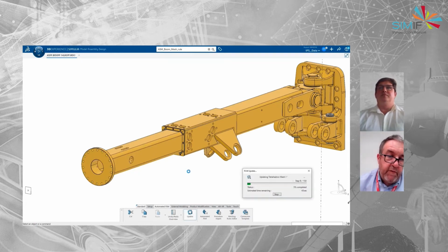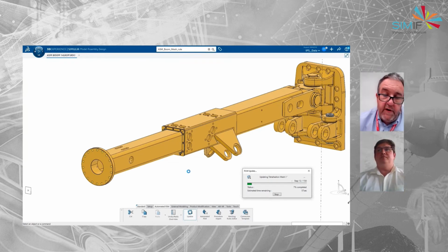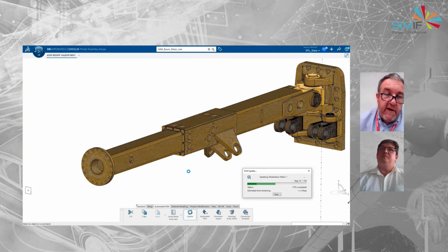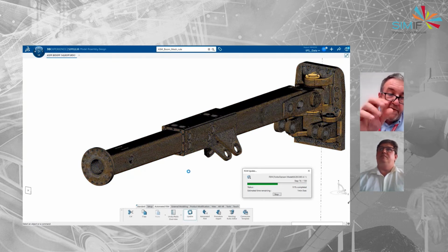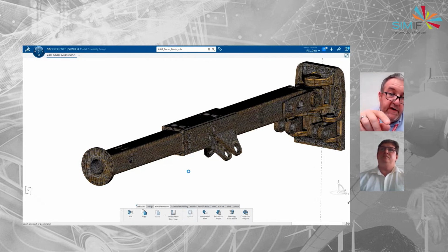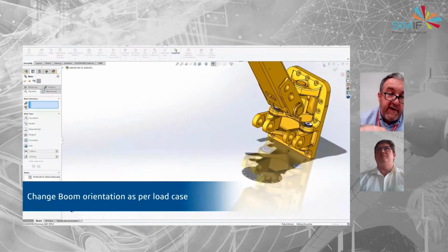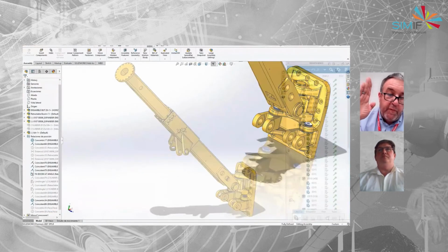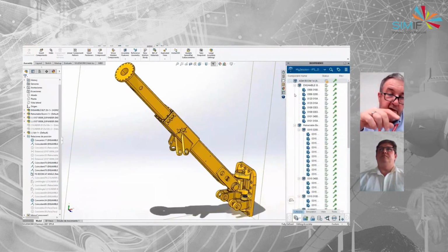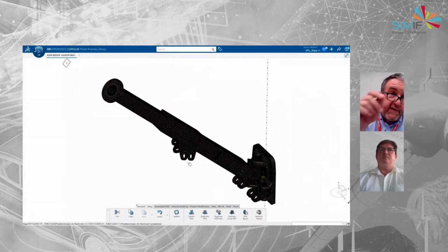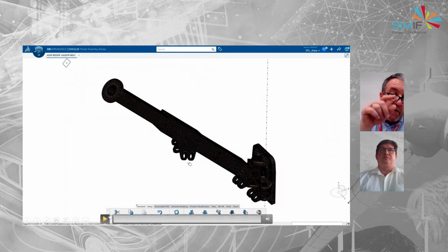And now, as you can see, we've got some bits of information. The mesh rules have now run through there. Everything's going meshed on there, which again, one of the benefits here is, if we make changes, it recognizes the geometry. As you can see here, we're going to lift the boom arm up very quickly to then modify that and apply that same mesh to the new assembly in the new position. So very quickly that updates that whole geometry.